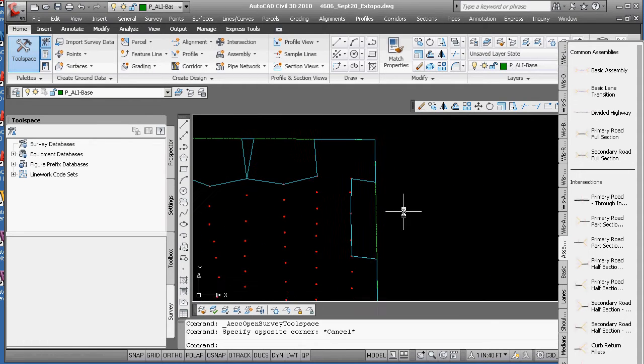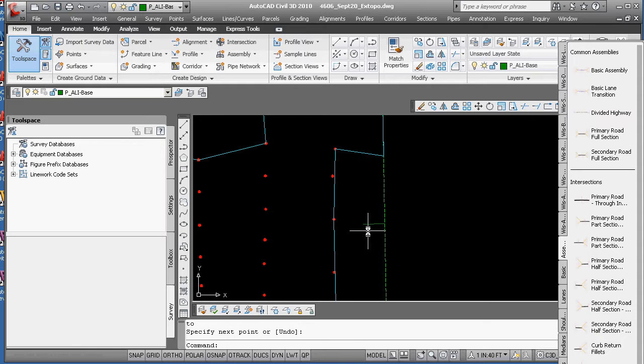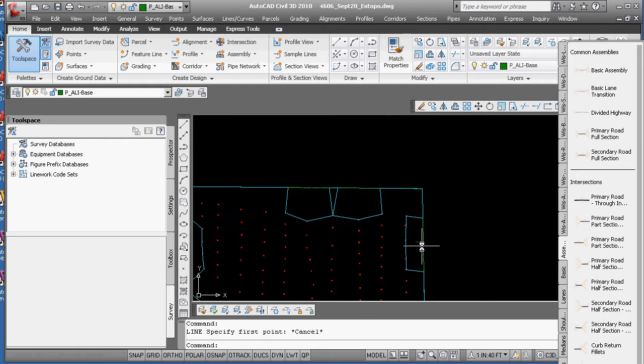All right, I'm going to draw a line from here perp to, and then realize it's going in the wrong direction. So I'm going to left click in the middle, space bar, rotate 180. When you do a polyline edit, it will take the direction from the first line.